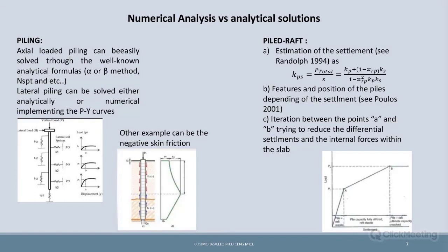So we have to watch out when using this formula. The same happens for the piled raft foundation. For example, regarding the settlement I was speaking about before, most designers use piled raft foundations to avoid or mitigate settlement. If we are in Asia, we can use, for example, the formulas from the Hong Kong piling manual of 2000, or we can use the 1994 formula of Randolph, which is a formula